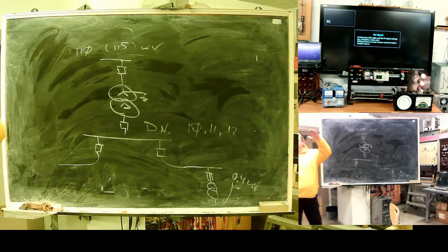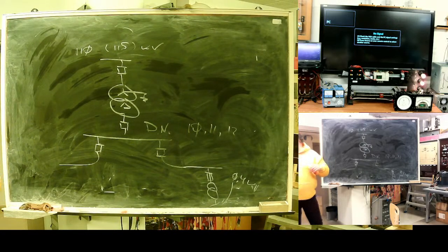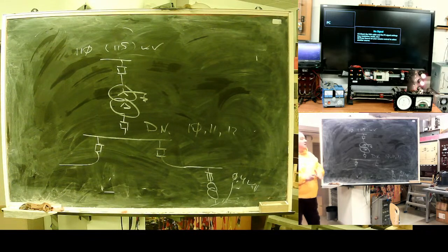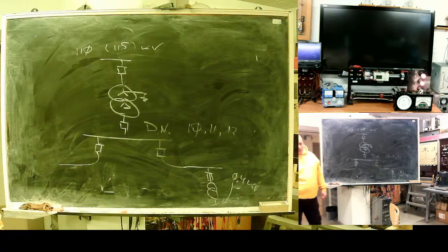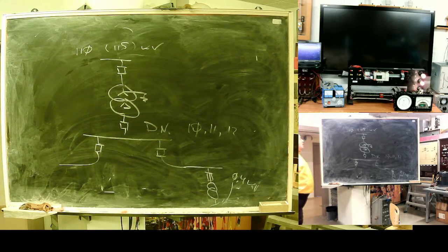Otherwise, you will see voltage outside allowable margins. You can go down by 5%, and you can go up by 10%. These are your margins for voltage quality. Otherwise, the public utilities regulator, SPRK, Sabiedrisko pakalpojumu regulēšanas komisija, the regulatory commission for public services, will find you. Meaning, what you need to do is compensate this load change.